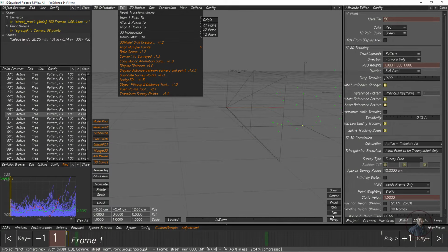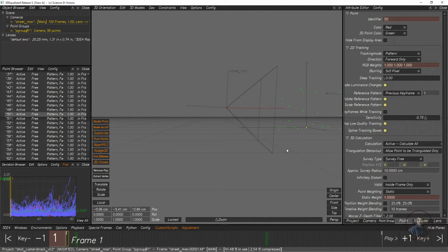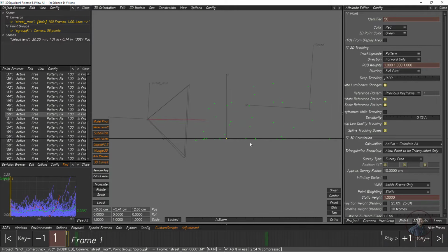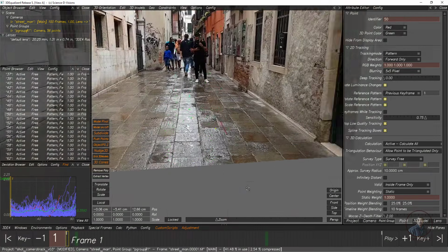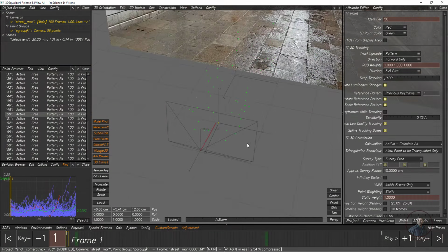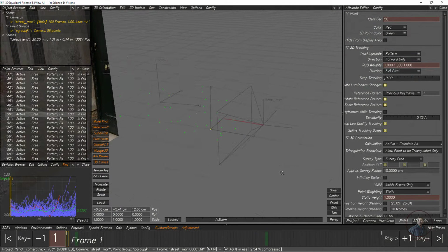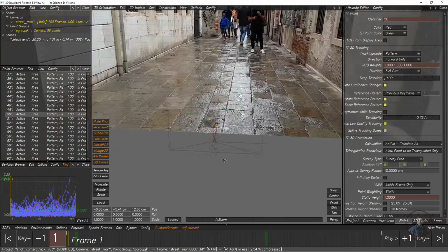Now if you select this side view and click on perspective, we get this orthographic view. Now you can see all these points are placed on top of our grid, and this is our origin. So like this you can orient your scene inside 3DEqualizer. First we define 3 points on our ground which define our XZ plane, then we select 1 point as the origin.